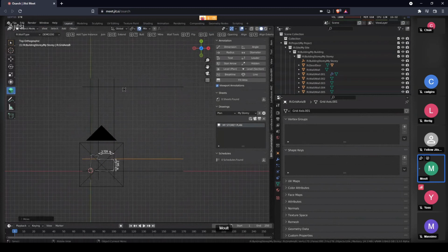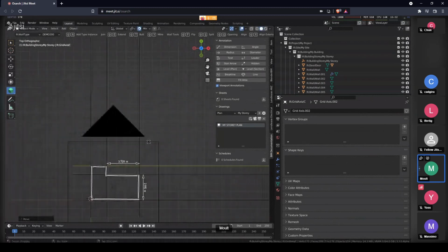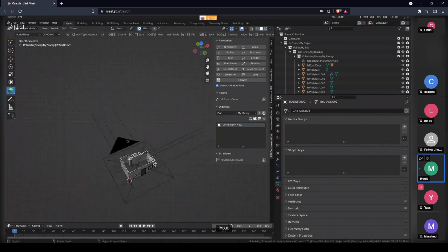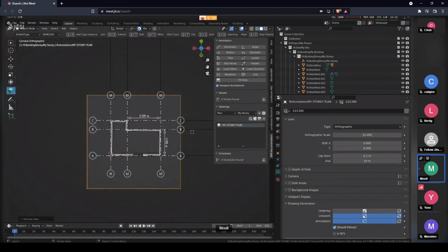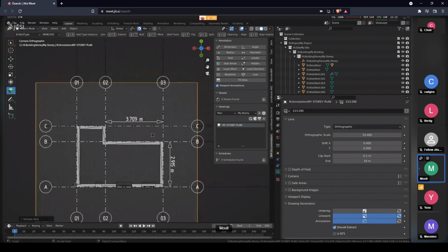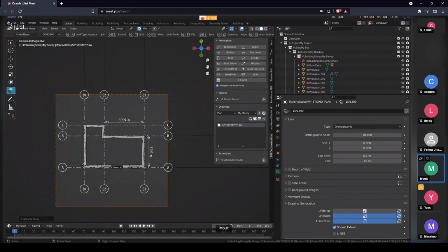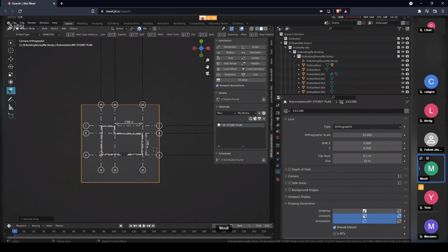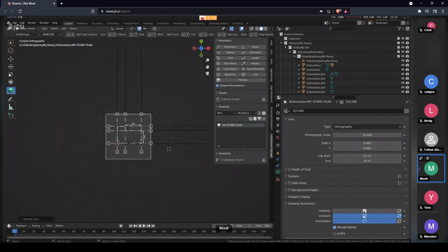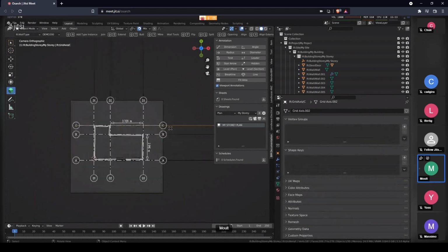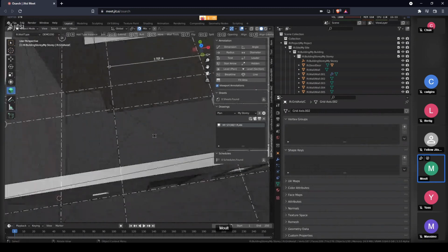move that grid line over here and over here. You'll notice I've just moved the grids, but the extents of the grids are still way outside my drawing, and that's okay. Now if I reactivate my drawing, I've now added in some grids. You can see it's automatically generated grid annotations for my drawing. And not only has it automatically generated it, it's automatically clipped it to my drawing boundary, right? Because the original grid is very far away.